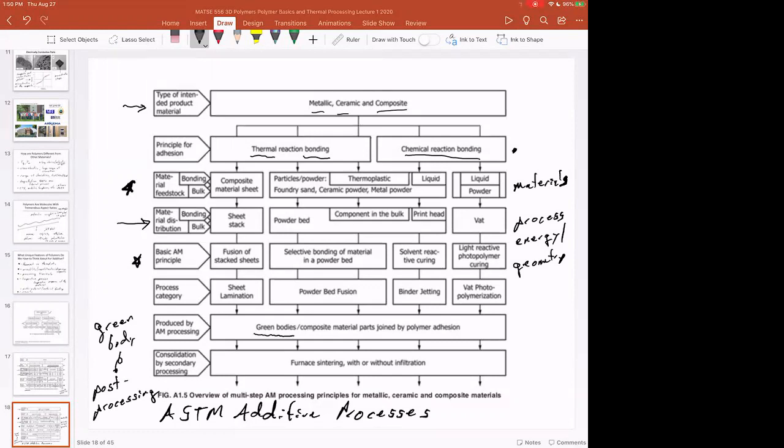And so you have your SLA process, there's lasers, you know, it's cool, you have shapes appearing out of your vat. That's really awesome and interesting, and that's what a lot of us are here to learn about. But that part that just came out of an SLA process, say from Carbon or someone like that, needs to be solvent washed, needs to be thermally cured.